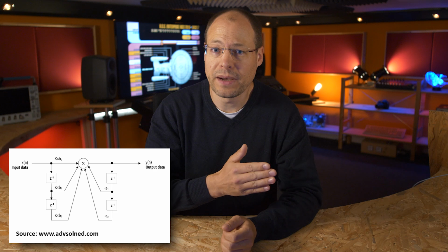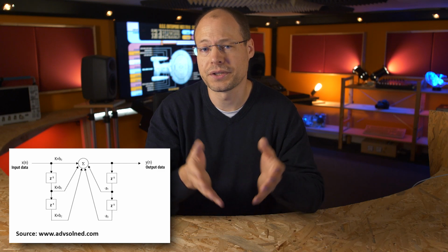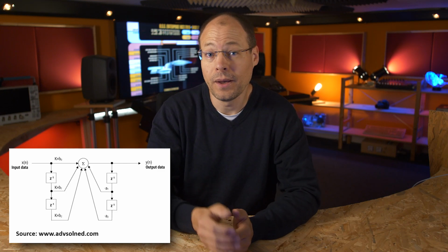That's why we should take a closer look at the IIR filters first. With these filters, 2 or more previous samples are used to weight them with coefficients. This becomes a little clearer in the graphic of a so-called biquad IIR filter configuration. Here we have a forward path for the input samples and a feedback path for the output samples, each with individual multiplicators called coefficients. Plotted as an equation, this looks like this.